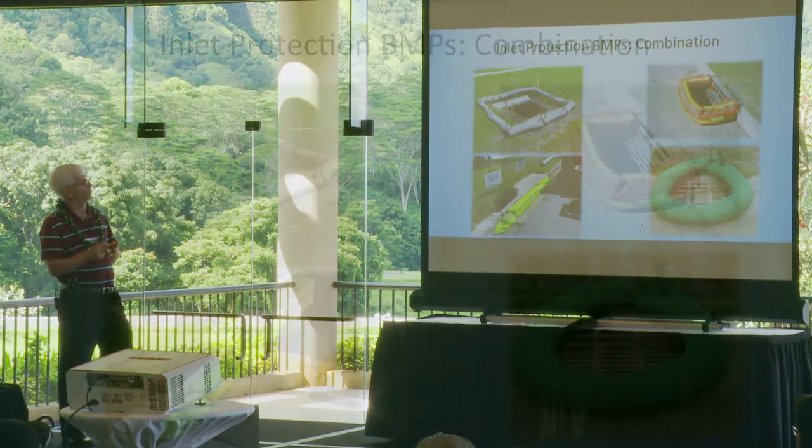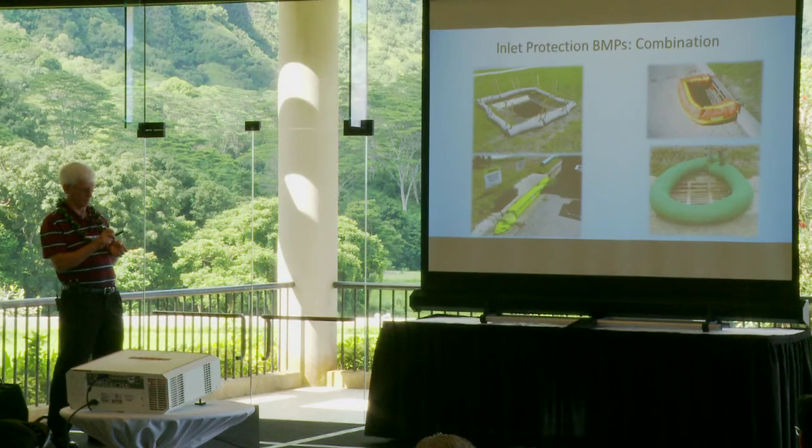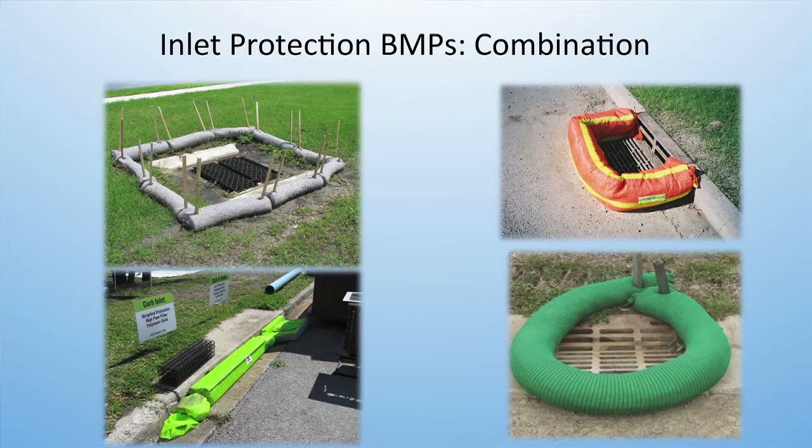Here's some modified synthetic wattles. Some of these come with a stiffener wire in them to allow you to build angles on them and hold them in place. Some of them you have to modify and make a loop on them, like this one. This one is a plastic skeleton with a geotextile on it, and at the end it has space for you to put rock for weight, so it has kind of like a built-in rock bag, sandbag capability. These are all better than a standard.